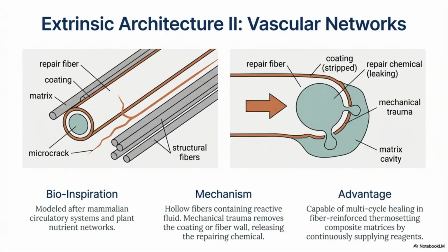Extrinsic architecture uses microencapsulation. Urea formaldehyde microcapsules contain a healing agent in an epoxy matrix. A crack ruptures the shells, releasing the agent to contact a catalyst and polymerize, bonding the crack surfaces. The limitation is single-cycle healing due to reservoir depletion.